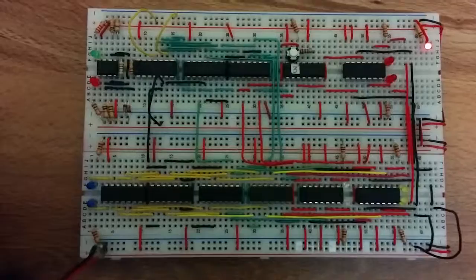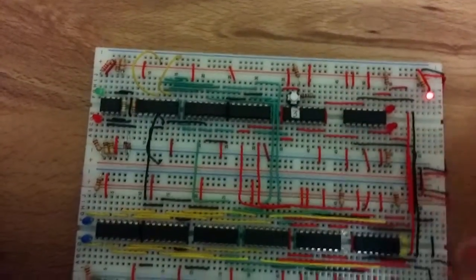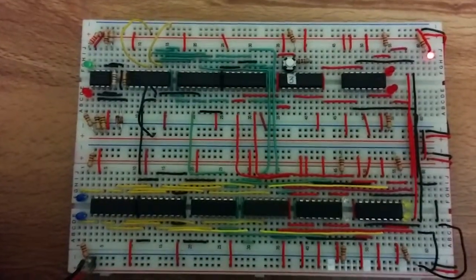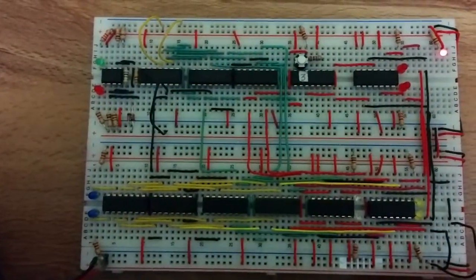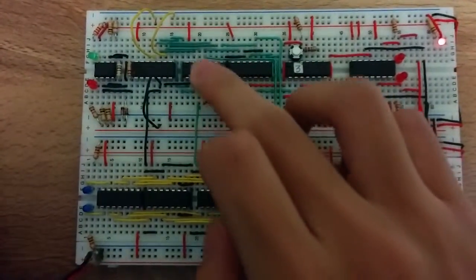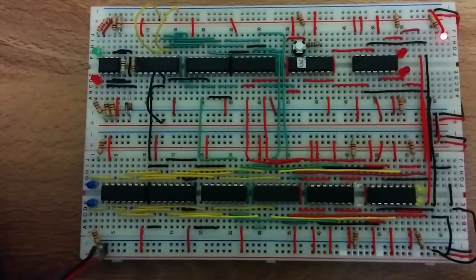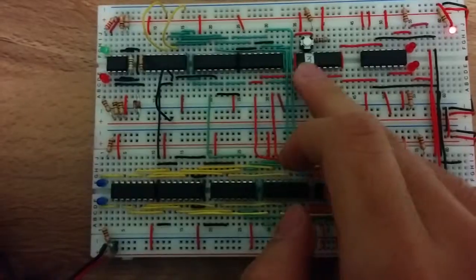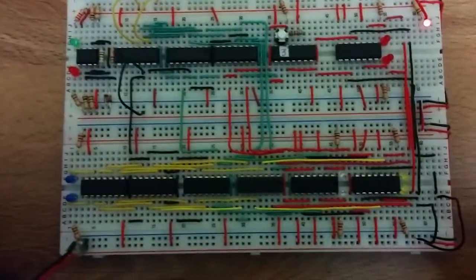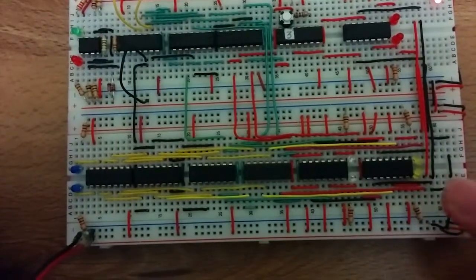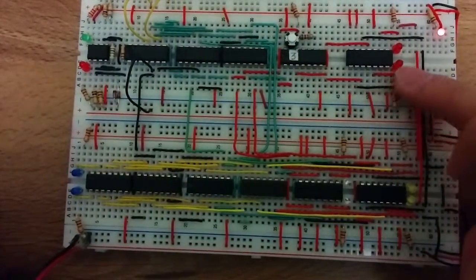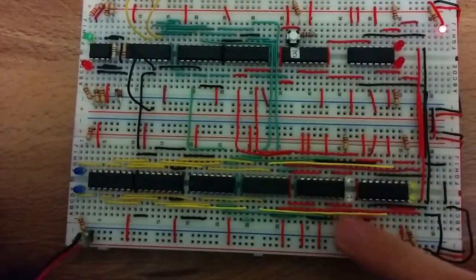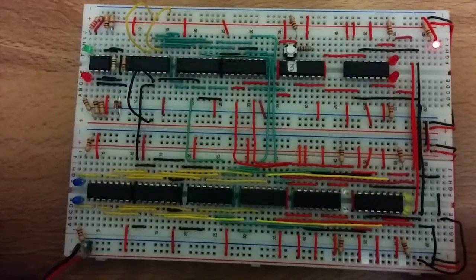In the actual circuit, the one that I have built, we have the address leads in yellow, the address encoder with the green wires around the 3 AND gates and 1 NOT gate. We have the data leads at the corner, the 2 black wires that connect to the three 7474 D flip-flops. The D flip-flops are our memory cells, and we have the 6 LEDs to indicate what is stored in their respective memory cell.